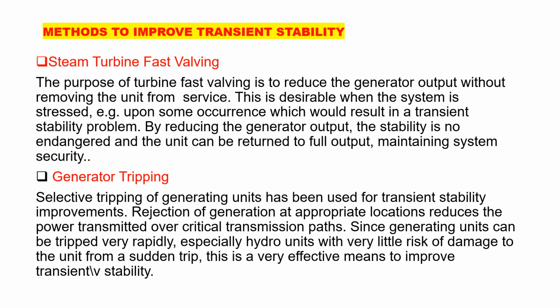In those lectures I have mentioned that through the transient state stability you can always locate those points at which you can separate the system and achieve a kind of islanding, and some of the generators are saved, and if they are an interconnected system, then all the systems do not go into the state of instability. So you save the machines and the power plant, and the total area breakdown does not happen. As you have seen in the case of Pakistan, many times you witness a total breakdown in Pakistan. That is a result of that.